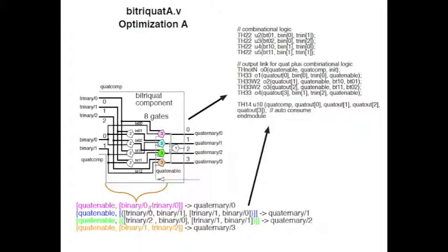So we can factor the terms of the equations into 4 input or fewer terms of and/or relations. And any and/or relation of 4 or fewer inputs will map to a gate in the NCL library. That's the whole point of the library. Okay, so that's what we're doing here. We're factoring the equations, mapping them into gates from the library, and that is our NCL circuit.